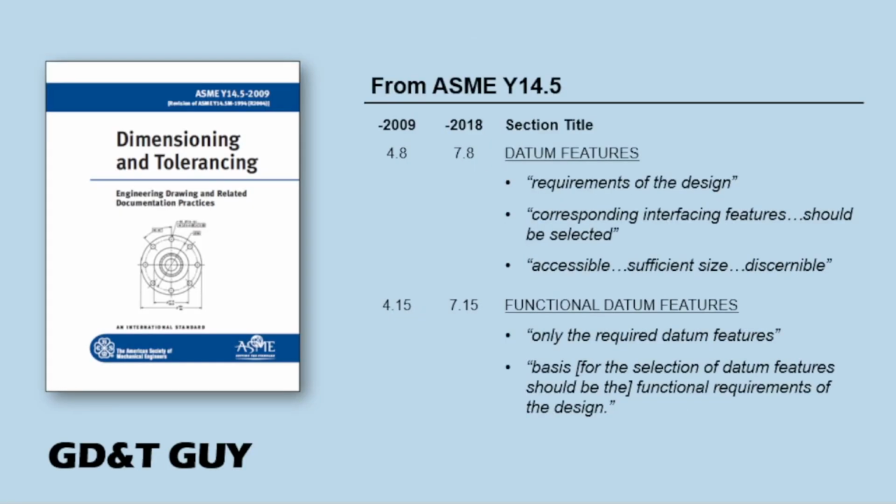The question is hard to summarize. To start talking about it is to open up multiple avenues into different, somewhat advanced GD&T concepts. And it all starts with some of the things the standard tells us about datum features, indicating that datum features are really best when they are the features that actually locate the part in assembly. We'll come back to this slide and these quotes later on.